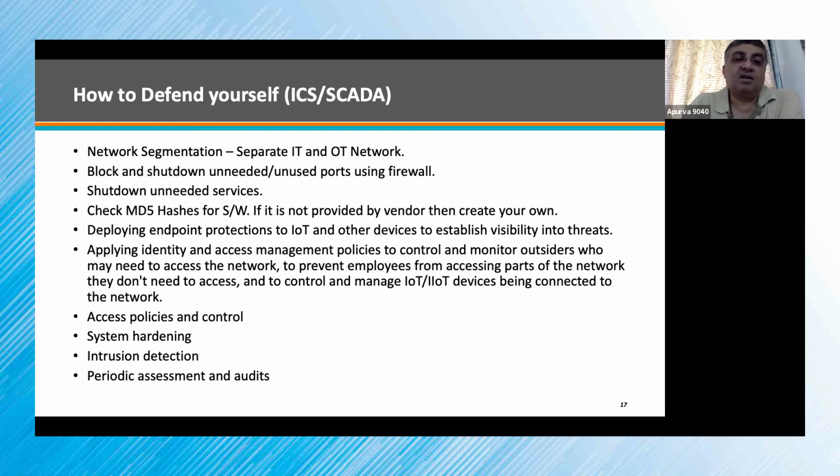Access control policies. Even in the SCADA system, you apply policies: who are the people who can do configuration changes, who will do only the monitoring part, all those things. System hardening, I spoke about. IDS: if you can implement IDS, some of the firewalls have built-in IDS, you can utilize those. And finally, the periodic assessment and audit of your OT system. Just like what you do for your IT system, you should do it for your OT system also.